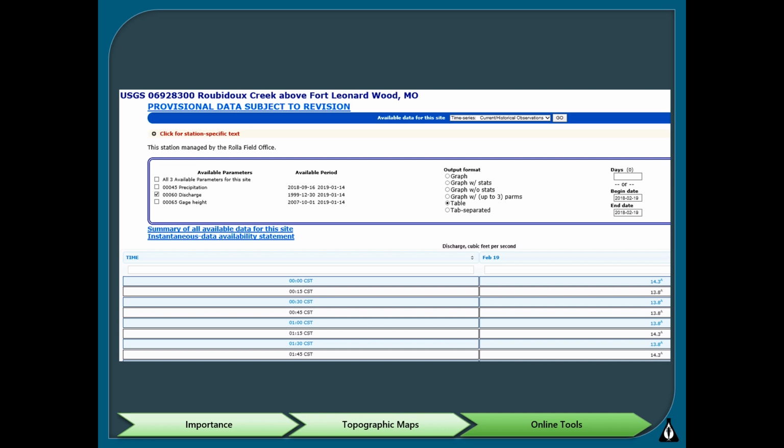This is an important tool to monitor river levels for your safety. As a reminder, the discharge data available on this site can be used to report on the discharge data sheet only if the gauge is located on the same stream within a half mile of where you're taking discharge, with no inputs or outputs, meaning no tributaries coming in or leaving the stream.